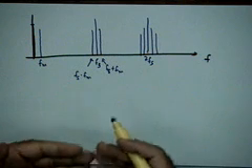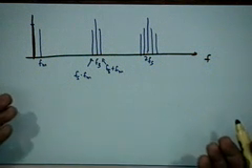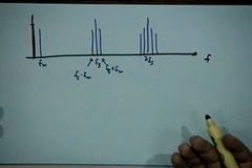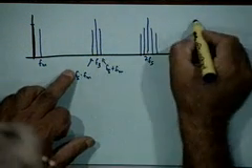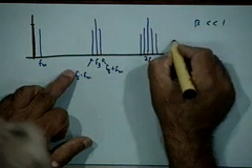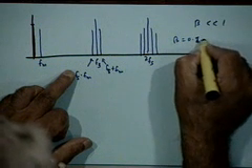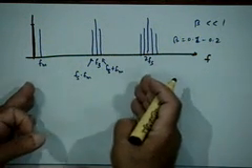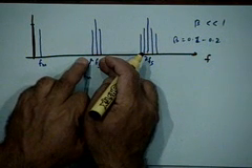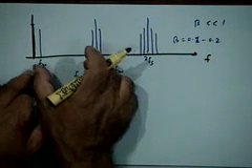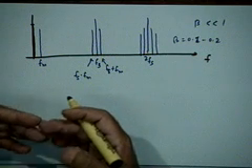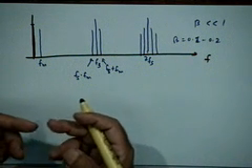So the demodulation for a PWM signal is once again the same low pass filter that you use for the case of PAM or a sampled signal. This is true when beta is small, typically much less than 1. As beta increases, you can have a larger number of components around Fs, and that will imply that the guard band you have against aliasing becomes smaller. So you have to watch out for that.